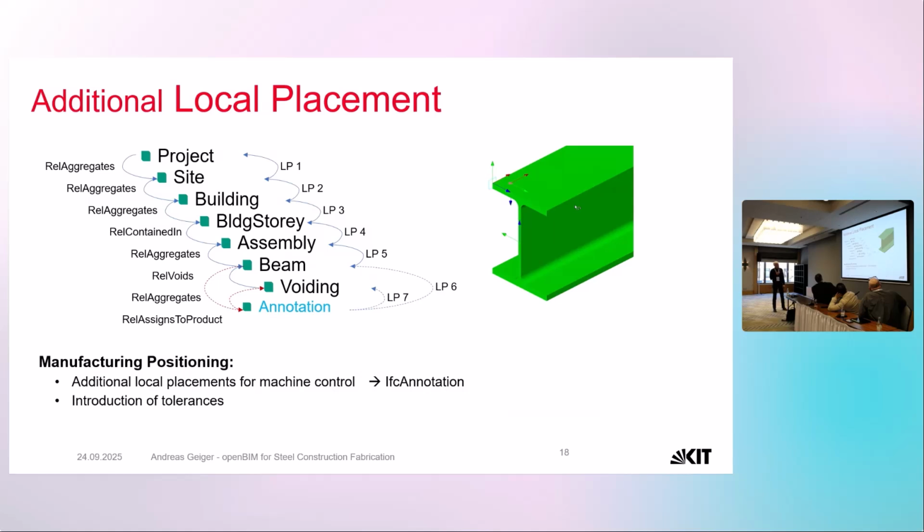Then also a very important part is we need an exact positioning for the machinery. So we have to define extra local placements based on IFC annotations. We have defined or developed this concept. And with this step, we were also able to introduce tolerances within this process that's completely new compared to DSTV.